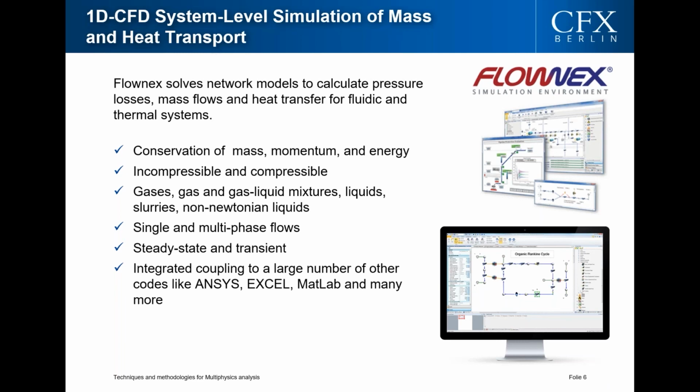and you can also have non-Newtonian liquids. You have single and multi-phase flows. In the same user interface, you can do a steady state simulation or a transient simulation. And a big advantage of Flownex, you have a lot of integrated coupling to a large number of other codes, like, for example, ANSYS and Excel and MATLAB, and also many more. So it means you can easily couple the 1D simulation in Flownex with a 3D simulation in ANSYS, for example.